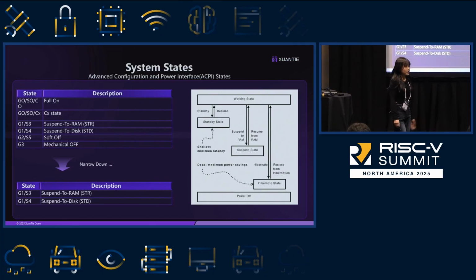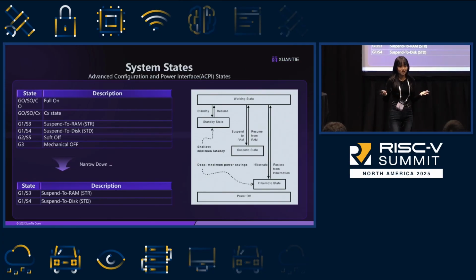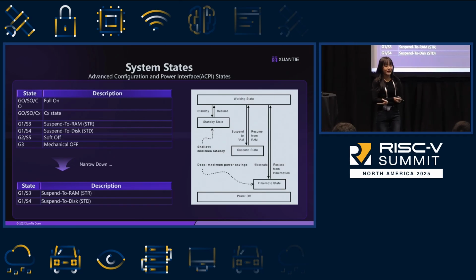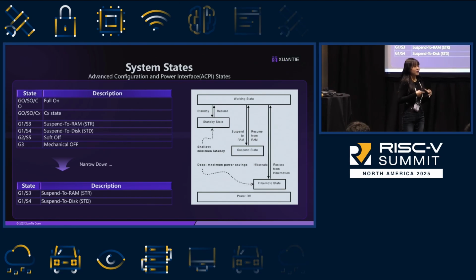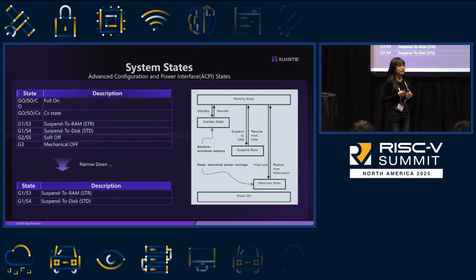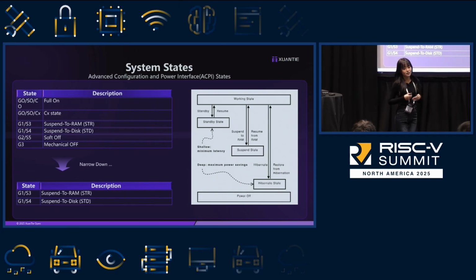Before I dive into my topic, I'd like to ask, what do you think a system standby is? The ACPI table defines the system states, separating them into 5 parts, from S0, which is the running state and wake-up state, to S5, which is a mechanical off. I'd like to narrow down the scope of our talk today to S3 and S4, which are the most practical in today's systems. S3 is aka Suspend to RAM or system standby, and S4 is suspend to disk.